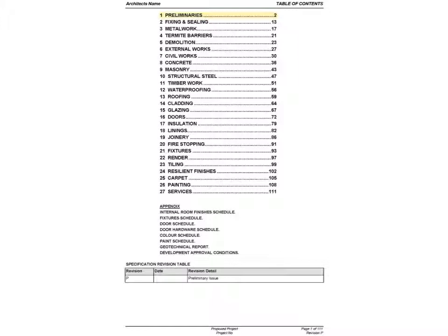No general requirements section is used, as the preliminaries is sufficient. Some say general requirements is for subcontractor detail and preliminaries for head contractor detail, but this is rarely the case. A technical spec is needed by both contractors. Head contractor only detail is best in the general conditions of contract.